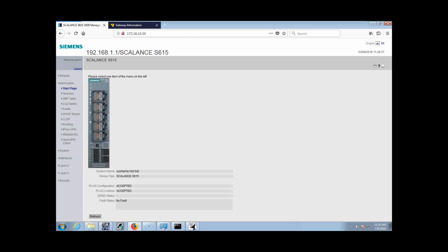An M874 device from Siemens that's cellular-based, and it is a Verizon cellular, and we could combine that with the S615 to provide the security function or even remote access at that point. In that case, we would likely combine it with SINEMA Remote Connect, which is software that you would get with your remote access device. It would allow you to configure user groups, who can get to what device, etc.